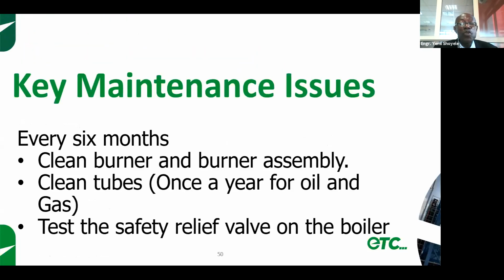In 6 months, clean your burner and burner assemblies again. Clean your tubes at least once a year. It's very important.